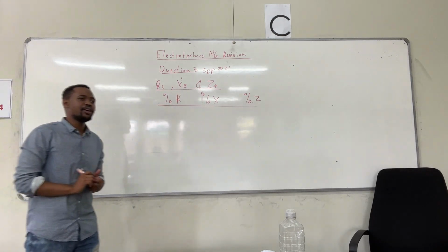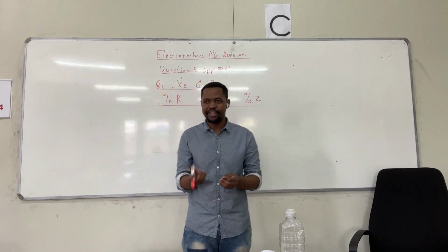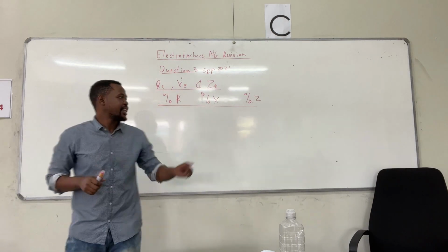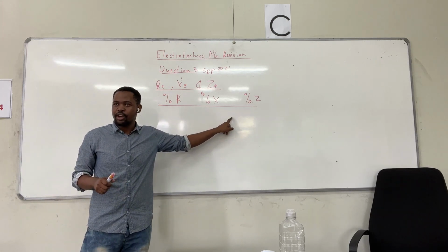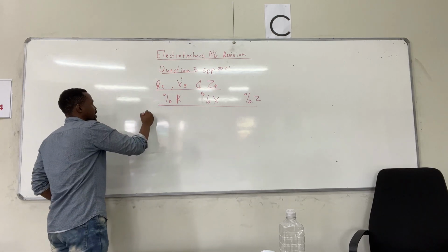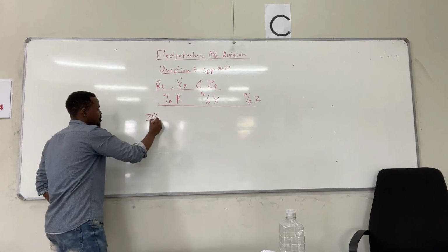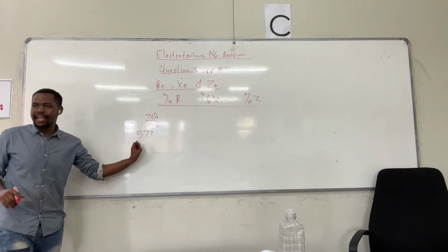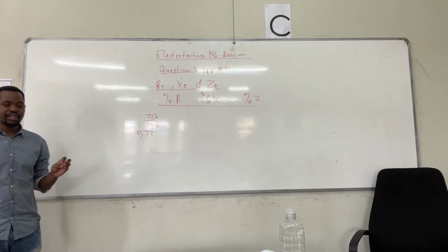It is because the manufacturer of the transformer, the person who manufactures the transformer, gives us these values in percentages or per unit values. A per unit value simply means that if the percentage was 72%, you divide it by 100, and it is in a ratio form.